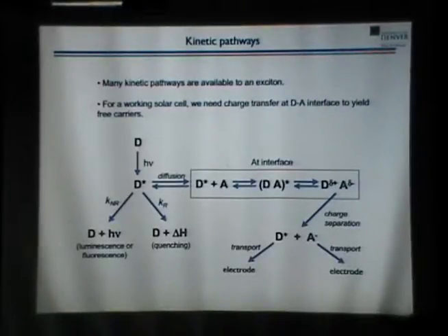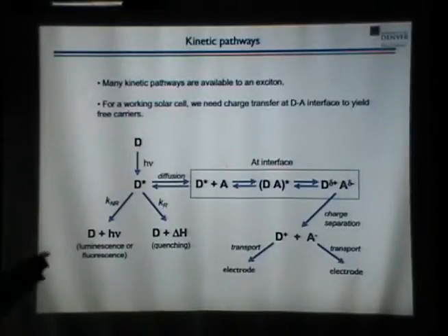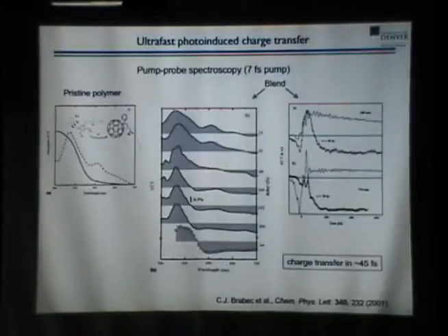It distorts the field around it. Now that polaronic energy, which would be a self-binding energy, is not particularly strong in these materials. So it's not necessarily a polaron in the sense that you would find it in some inorganic materials. But we still oftentimes refer to them as polaronic conductors. So anyhow, hopefully the positive polaron would go towards the positive electrode and the negative towards the negative electrode.